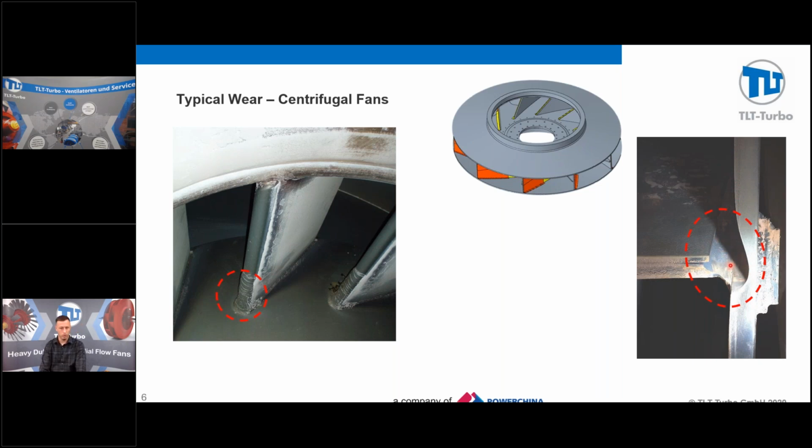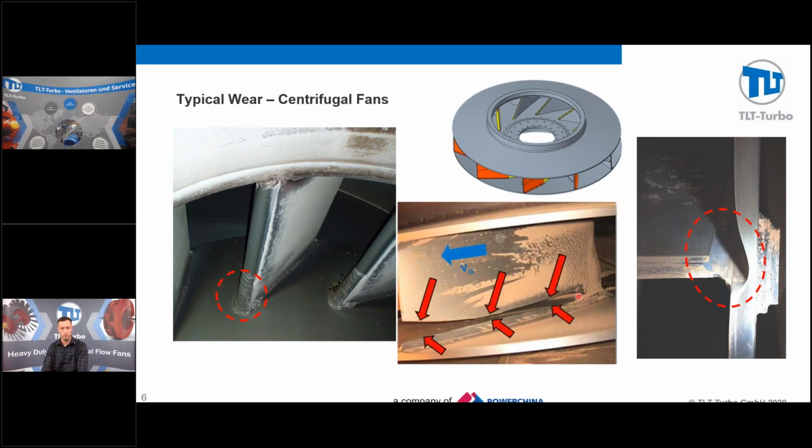And now we'll go to a little more aggressive example to show you a little more depiction of how far it can go. This is a scenario of a large wear groove inside a radial fan blade. It's working its way through here, and it's actually chewed itself completely off of the mounting surface. And you can see it's been doing it for a long time due to the wide gap here. So it's still wearing on the edge of that fan blade while it's in operation.